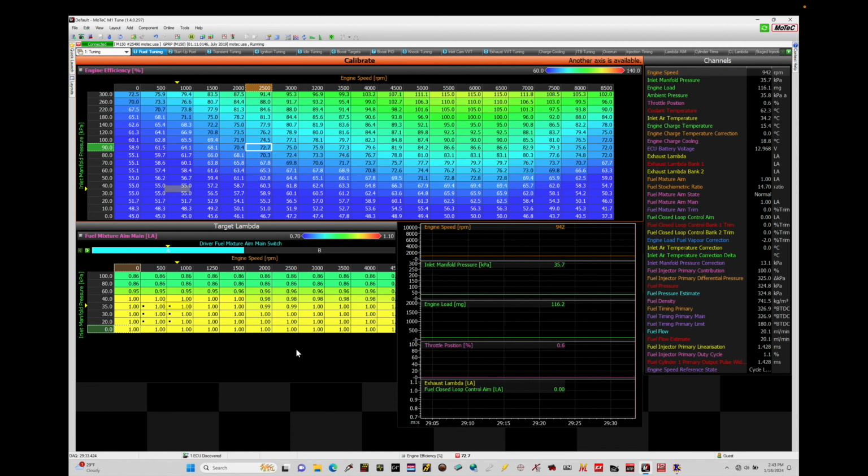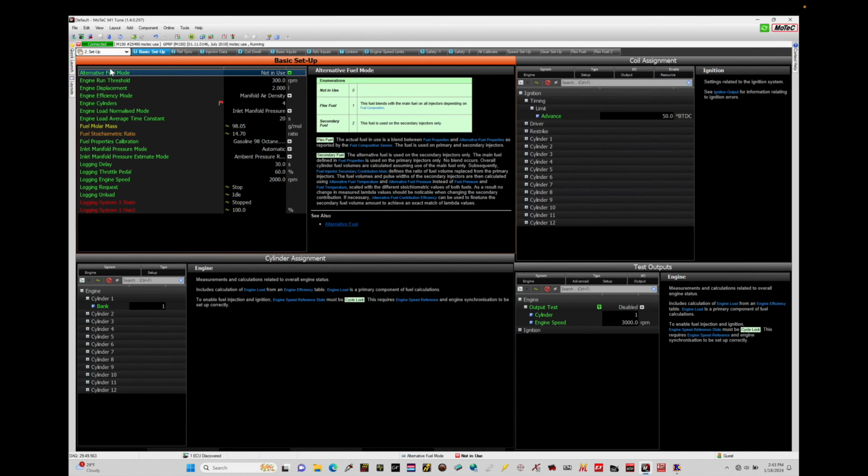We'll talk about the components we have to have wired in from our Motec to the vehicle, and then talk about our programming that we have to work with in order to make sure that the air conditioning is controlling correctly. So first things first, we're going to go here under our tuning window and jump down here under our setup. Now under setup, we're going to move across from our basic and go here into all calibrate.